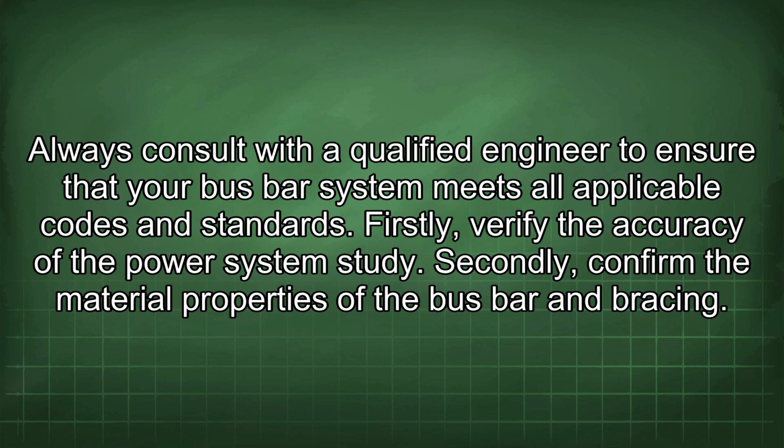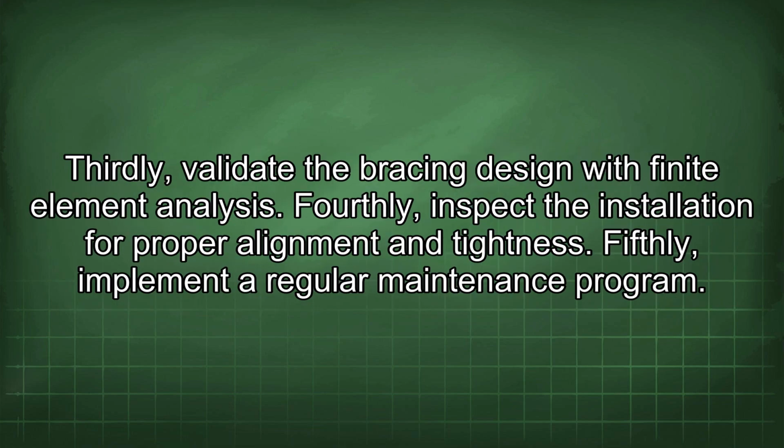Firstly, verify the accuracy of the power system study. Secondly, confirm the material properties of the busbar and bracing. Thirdly, validate the bracing design with finite element analysis. Fourthly, inspect the installation for proper alignment and tightness. Fifthly, implement a regular maintenance program.